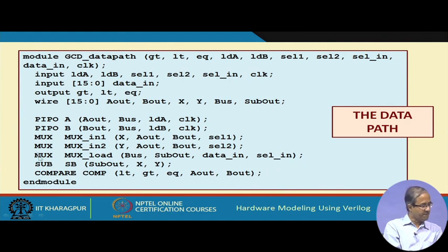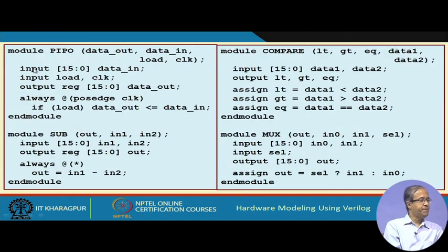Right now, this is a very quick look at these descriptions. For the sake of convenience, I have shown all of them in a behavioral fashion, but in a real design, when your target is to achieve higher performance, we often design many of the modules in a structural way, so that we have entire control over the way this circuit is designed. Because when you design in a behavioral fashion, we leave it entirely to the synthesis tool to decide what kind of circuit it will be generating.